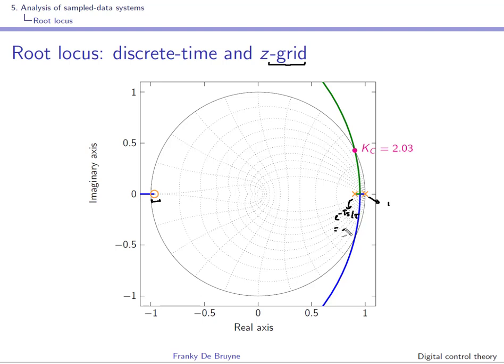So here this corresponds to the exponential of minus 1 over 10. So the root locus starts at the 2 poles, then the root locus moves towards the zeros like this. Here the 2 branches will encounter somewhere over here, and then one branch will go this way and the other one will go this way.